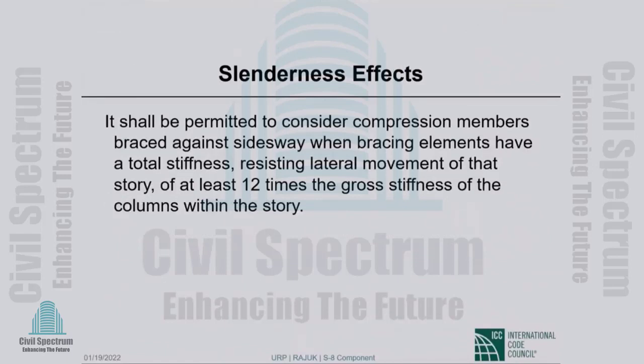It shall be permitted to consider compression members braced. This is again very important. Okay? So braced versus unbraced, sway versus non-sway.